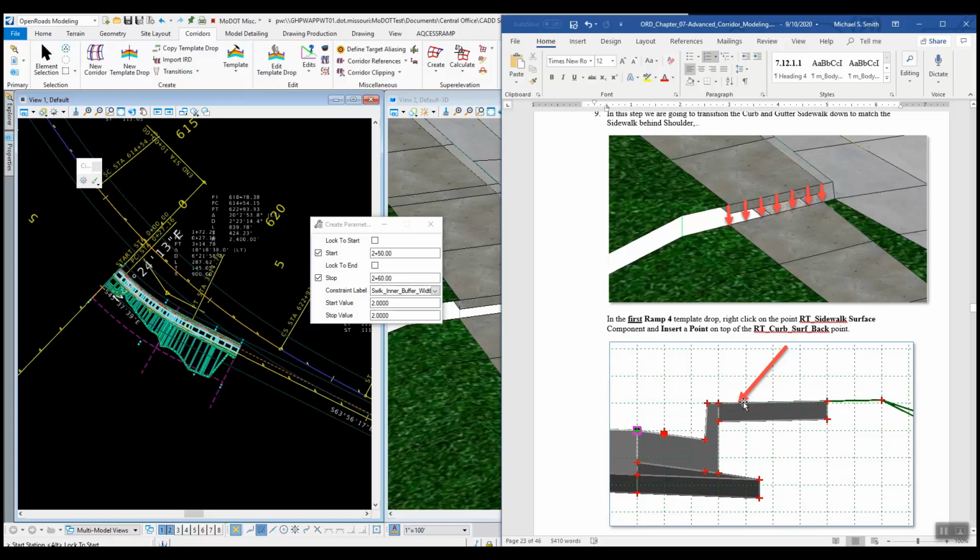And then that new point that we create, we're going to tie it to that location, the top of the curb, but as long as it's its own separate point, then we can adjust that sidewalk up and down. And then we'll probably have to go adjust our end conditions to look at other points throughout there, or perhaps this other right side to go back and look at that new point we created, so that when this moves up and down, this back one will move with it.